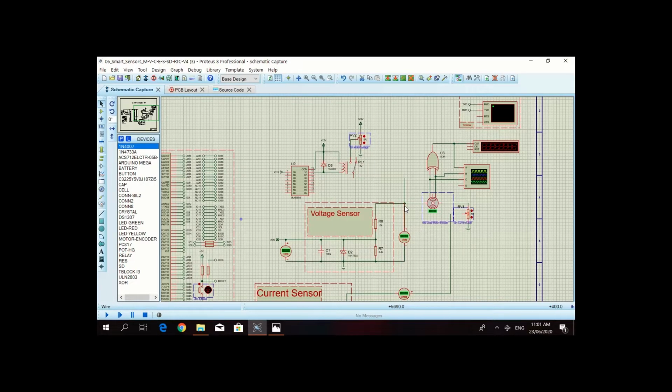Here we will be measuring it, and there are also resistors to make sure that there is no exceeding of the voltages and the currents. So when we simulate it, we'll have some particular voltage over this due to the motor. The voltage sensor has an input tolerance of 5 volts, so to avoid exceeding 5 volts, we have to use this.